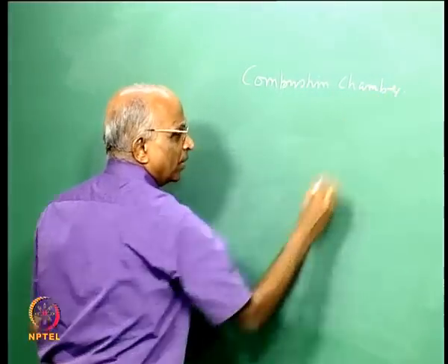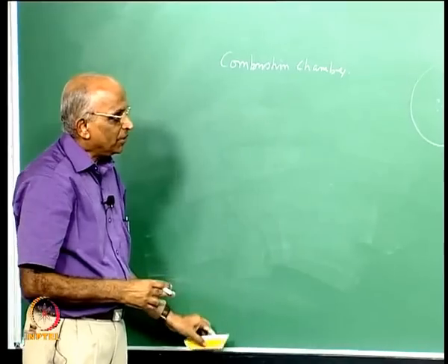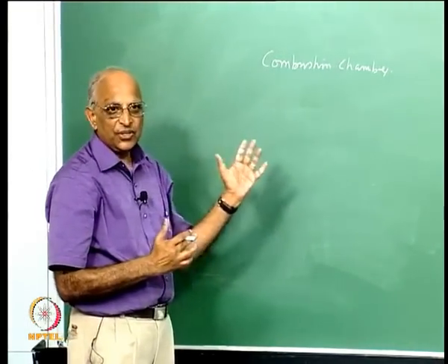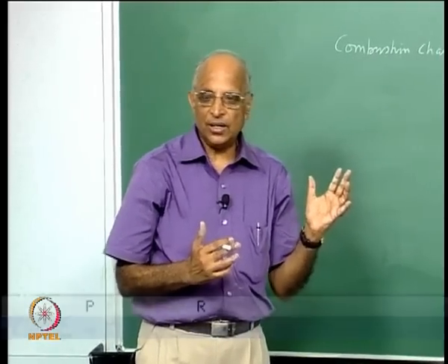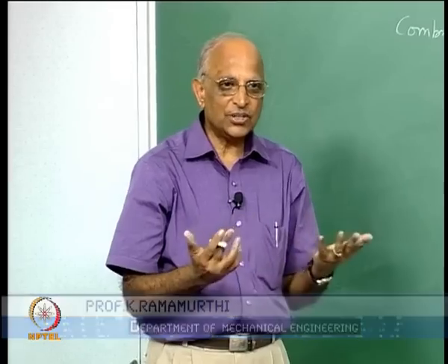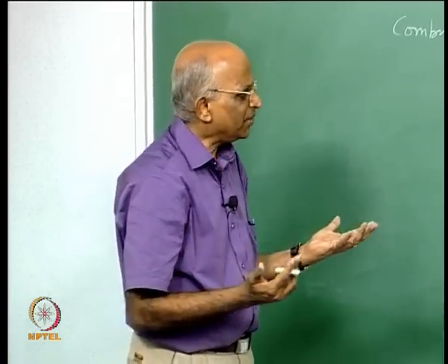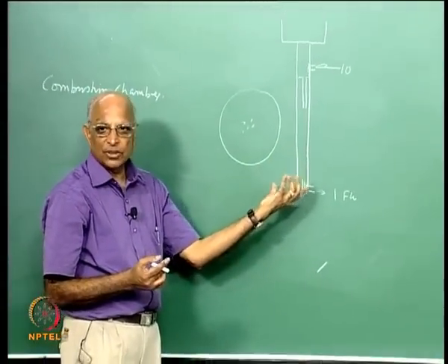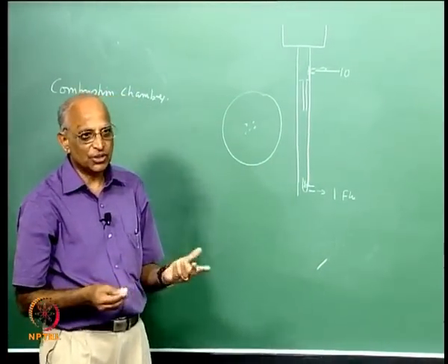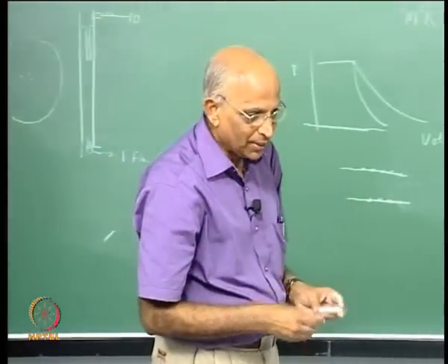Therefore, in this class what have we done? We started with the gas generator cycle. We looked at the deficiencies of a gas generator cycle, namely that some propellant gets wasted and is not fully utilized. Therefore, a staged combustion cycle and expander cycle are preferred, especially at high pressures. Then we just started with the injectors, and we looked at the shower head injectors. Maybe we will build upon this and look at the other injectors which are used in liquid propellant rockets in the next class. Well, thank you then, I think that is about it.